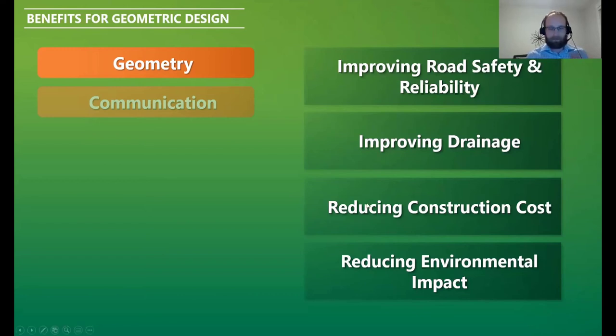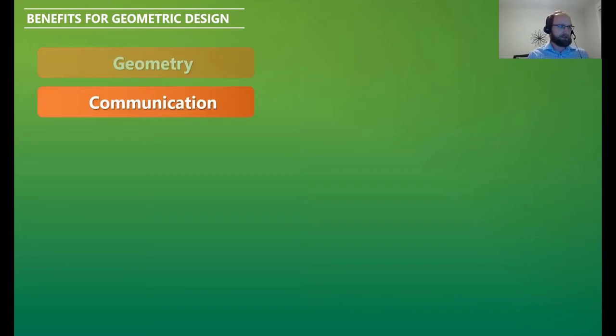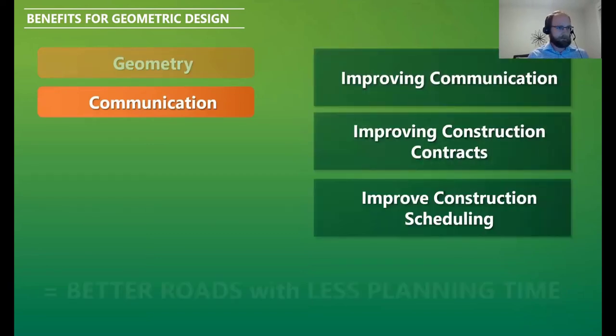But a big benefit from a cost standpoint is looking at things in quantitative terms rather than, oh, that's a difficult road. The driver for your construction costs is going to be how much dirt you're excavating and how far you have to move it. So with the design software, you can get updates for earthwork volumes and mass haul movement in real time to make more informed decisions. Now that costing function is also beneficial from a communication standpoint.